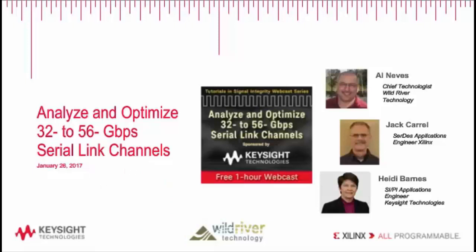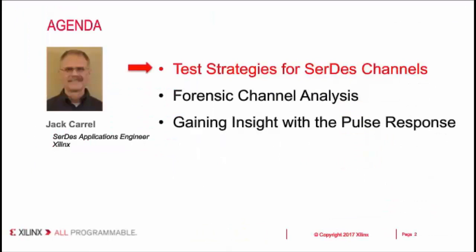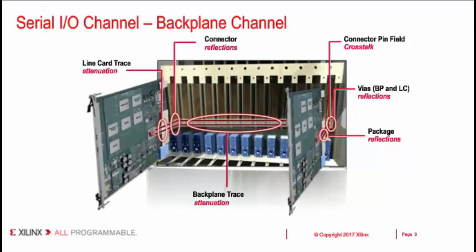Thank you. I want to begin our presentation by framing it as an application. Let's say that we want to have some product where we want to communicate between two cards that are plugged into a backplane. And to move a lot of data, we want to use a serial I/O over those channels. And immediately we begin to see that there's a structure to that. We're going to have the daughter cards and the traces on those cards and the attenuation that they represent. We're going to have connectors and the reflections and crosstalk that are involved with using those that have to be understood.